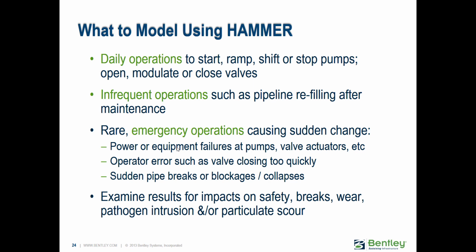Starting up your pump, maybe it ramps up a little bit. Maybe you're shifting speed of the pump. Maybe you're opening or closing a valve or hydrant at a reasonable rate, or your standard rate, and then see if your normal operating conditions are or would be a problem as far as transients.